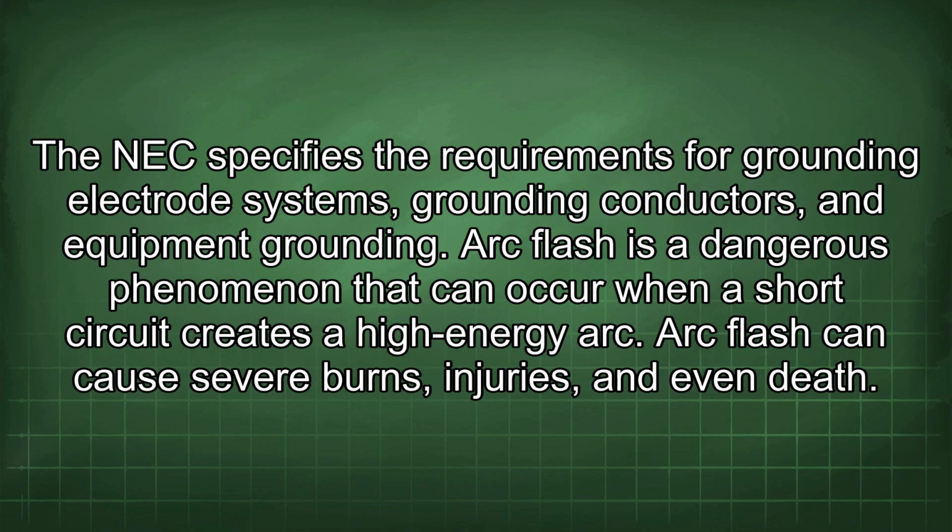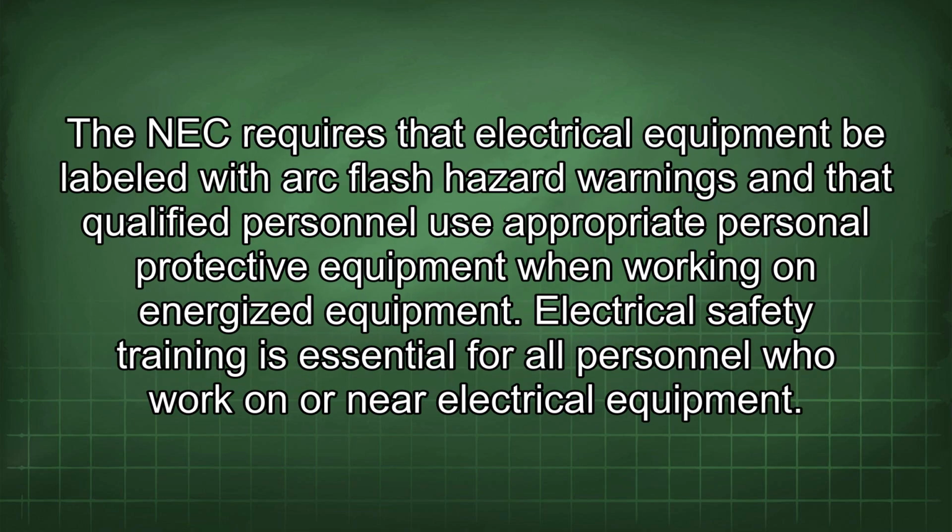Arc flash is a dangerous phenomenon that can occur when a short circuit creates a high-energy arc. Arc flash can cause severe burns, injuries, and even death. The NEC requires that electrical equipment be labeled with arc flash hazard warnings and that qualified personnel use appropriate personal protective equipment when working on energized equipment.